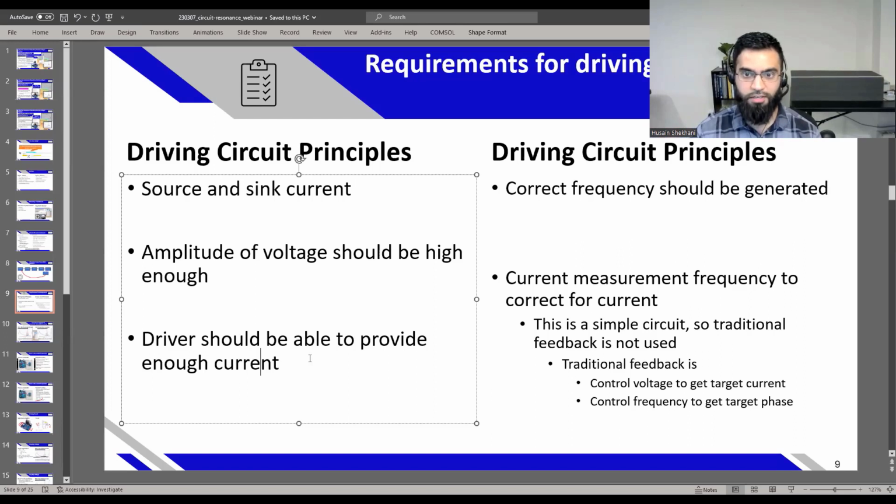So if you're driving at, let's say, 10 volts, and your transducer wanted, let's say, 1 amp, but you can only provide 500 milliamps, the voltage will actually decrease on the output side of the amplifier to meet that maximum current. And it'll heat, and it'll basically not deliver the maximum power to your load. That's what's going to happen. So it'll still work theoretically because there's an output impedance. There's a drop in voltage in the circuit.